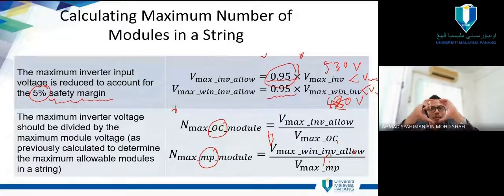So that is the margin, so that in case the modules overperform, the voltage will not exceed the highest rating. If we adjust exactly for 530, or 420 maximum, but it goes to 435 for example, it will stop. The inverter, if it is not in that range, will stop automatically because the switching is already there.